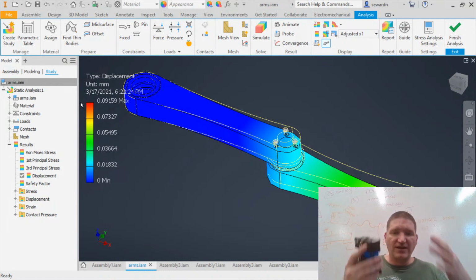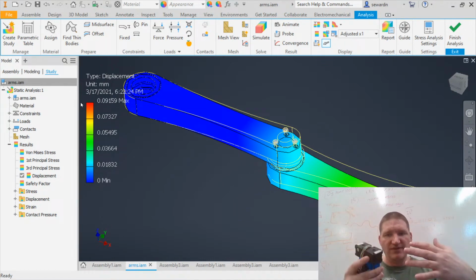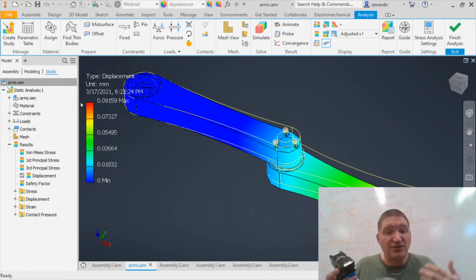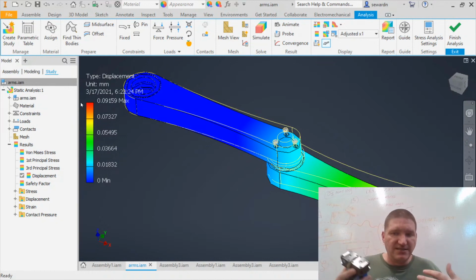And remember, whenever I have the arms together, the gravity is going to load things consistently. So if they sag, they sag. As long as I get consistent precision, I can use mesh bed leveling and stuff like this to hide some of my sins. So I'm not too worried here.